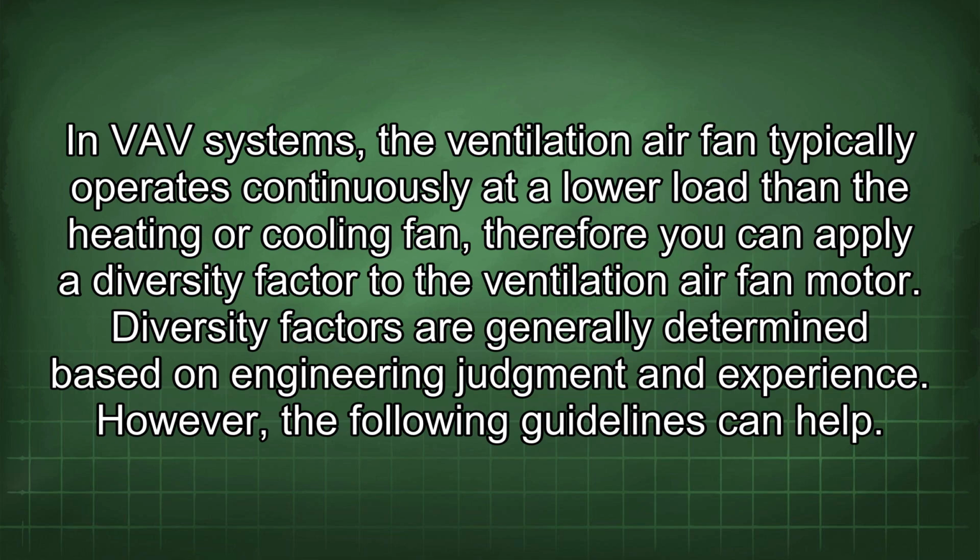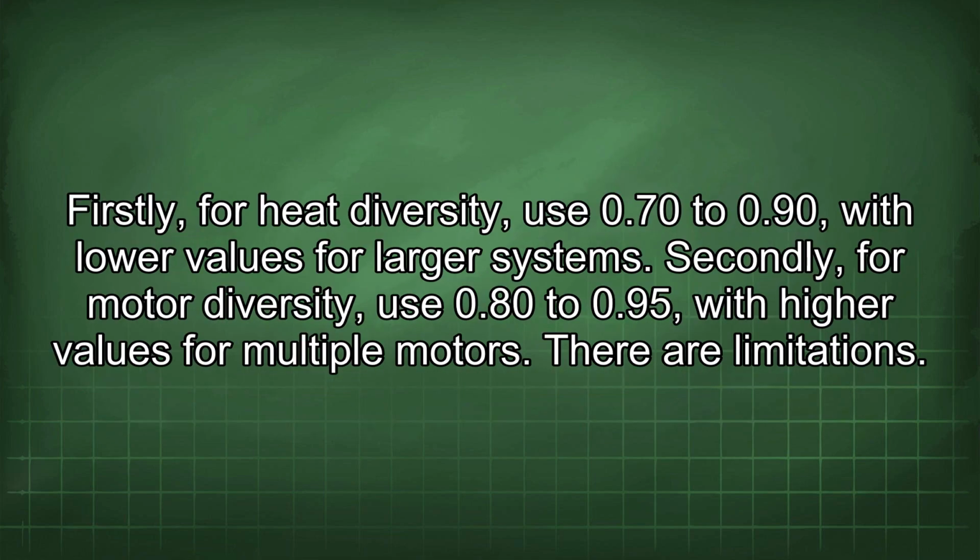Diversity factors are generally determined based on engineering judgment and experience. However, the following guidelines can help. Firstly, for heat diversity, use 0.70 to 0.90 with low values for larger systems. Secondly, for motor diversity, use 0.80 to 0.95 with high values for multiple motors.